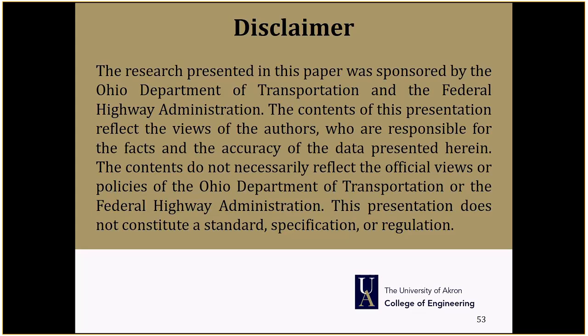But water may be seeping or passing through the underside of the membrane from somewhere else because the bond itself is not perfect. So the bond between the membrane and the deck is not adequate or good enough, and therefore water may be seeping from somewhere else. It's not necessarily because of differential movements of the beams itself. That's what we think. Perry, you want to?